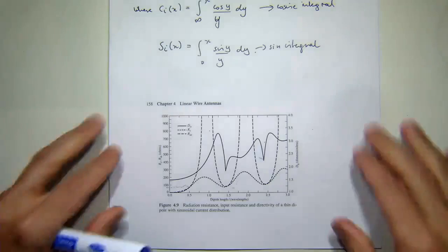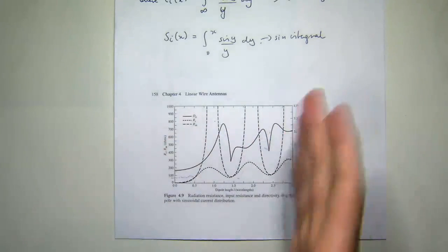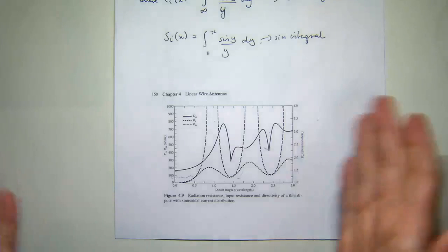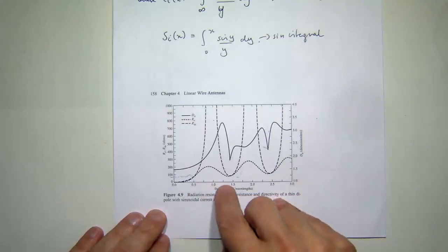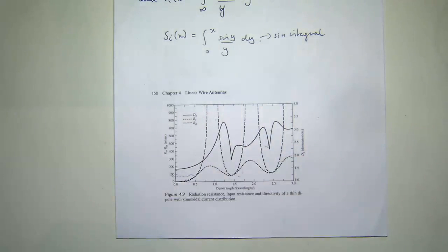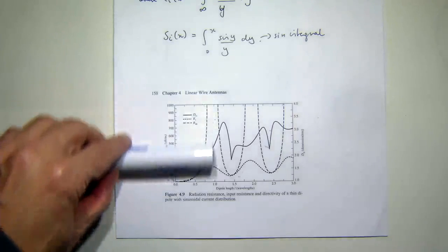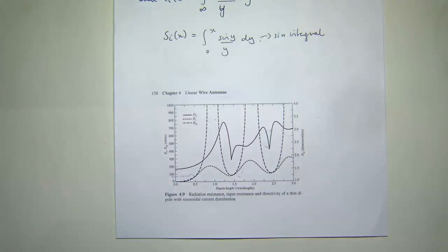And the other thing that this graph showed us is, as the dipole gets larger, increasing from about 3/4 of a wavelength to about 1.5 wavelengths, the actual input impedance, which is the radiation resistance plus all the other components required in order to set up that field, becomes asymptotically larger and tends to infinity, close to almost 0.8, 0.9 of a wavelength.